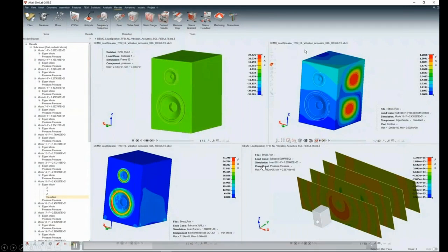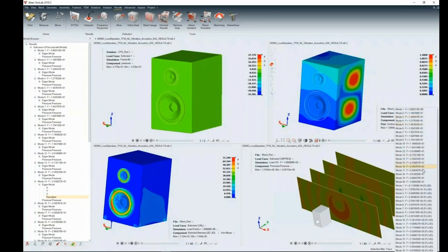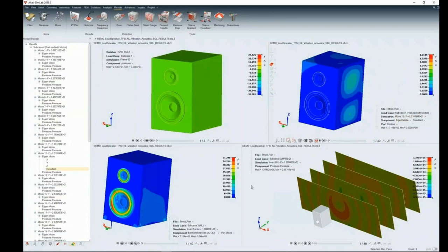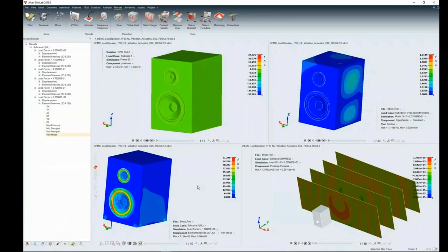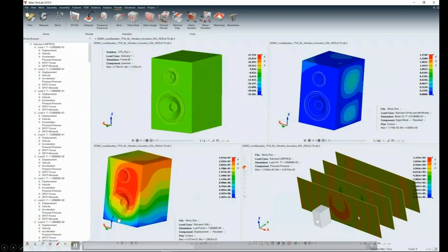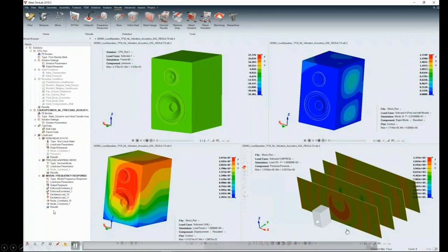So you can save the solutions I showed you previously as a template. And also, in terms of getting your results, you can conduct DOE studies by changing parameters like thicknesses, materials, and geometries coming from your CAD sync in SimLab. All of this physics in a single GUI, including optimization, is what you can do in the SimLab environment.